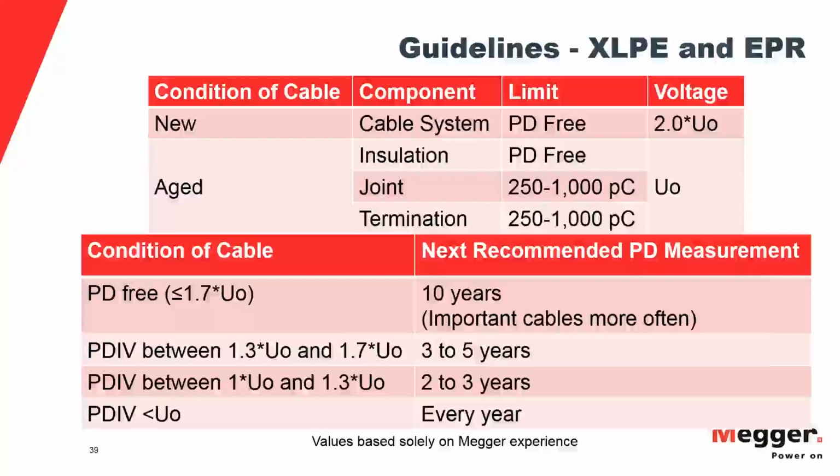Yes. The short answer is yes. Let's discount sine wave for the time being and talk about the other two, square wave and triangular wave. As the cable capacitance gets larger and larger, if you apply a square wave, it will get closer and closer to a triangular wave, just because the long cables filter out the high frequencies, and those sharp edges on the square wave will get slower and slower. So eventually, they'll become the same wave.